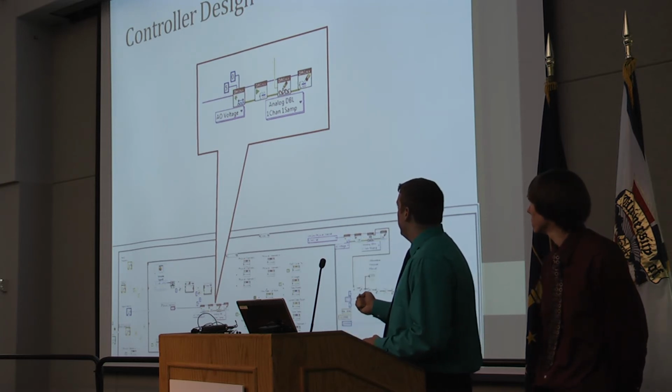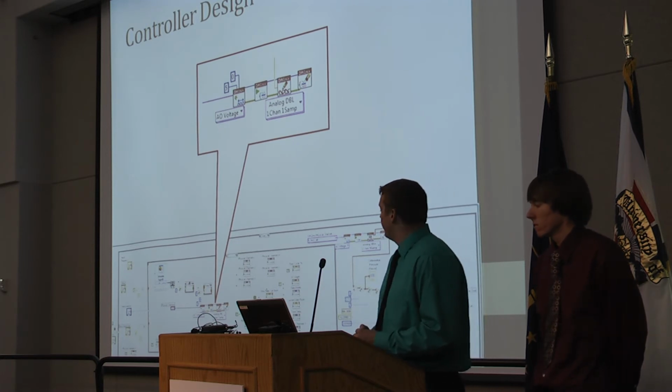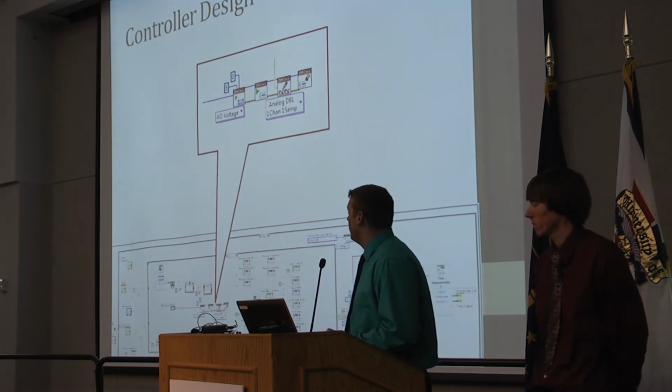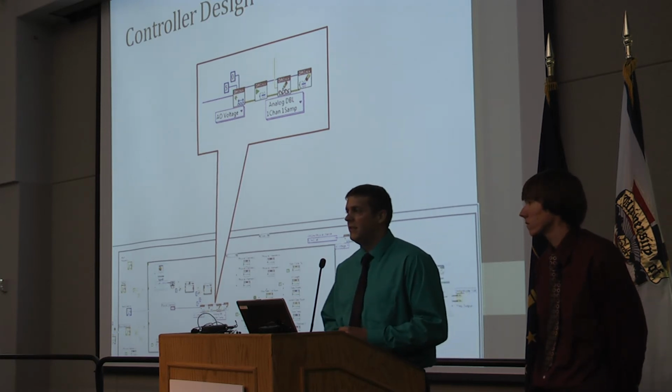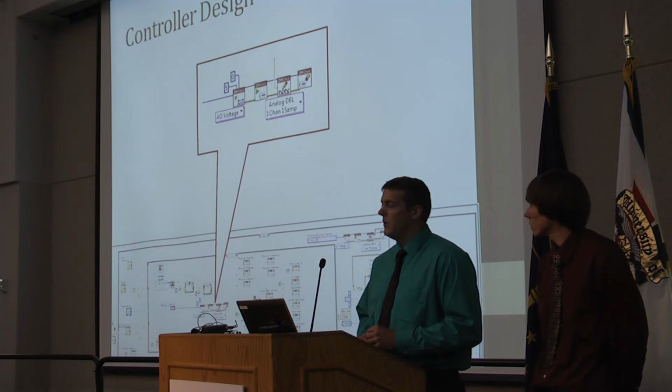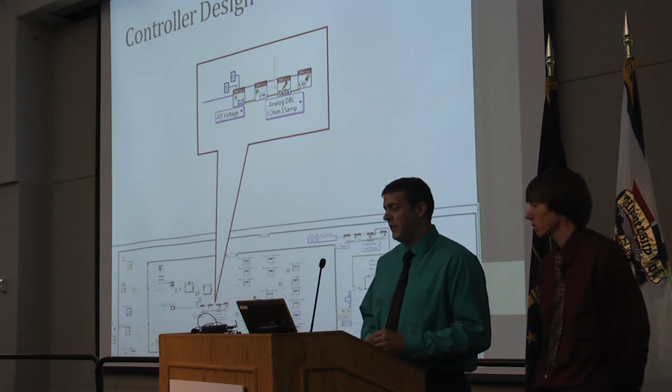So in one of these blocks, you define the limits, where we define 0 and 5 again as a second check. And then we also have to define what is being sent, and this was an analog voltage, and the physical channel that's being sent on, which is just the port on the NI interface that the pump is connected to.